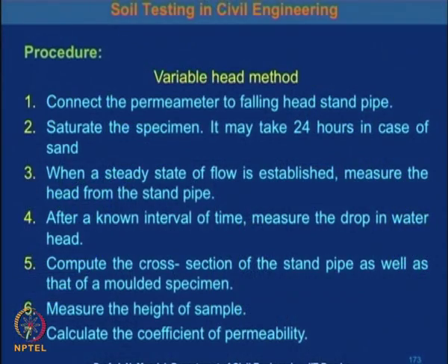Now, we can discuss the variable head permeability. What is the procedure for the variable head permeability? We connect the permeameter to the falling head standpipe and saturate the specimen; it may be 24 hours in the case of sand. When a steady state of flow is established, measure the head from the standpipe.